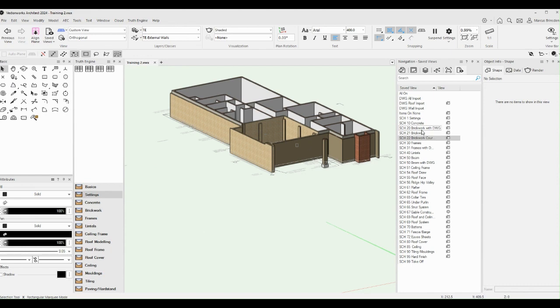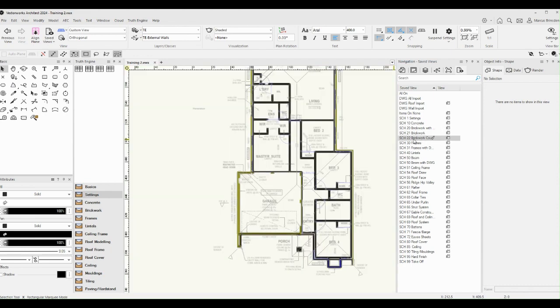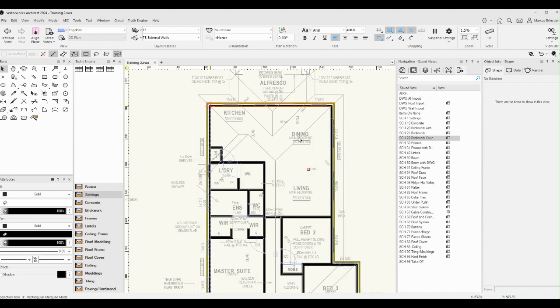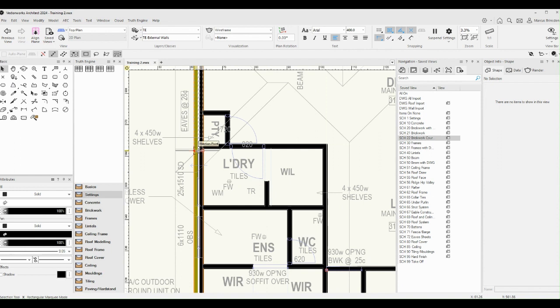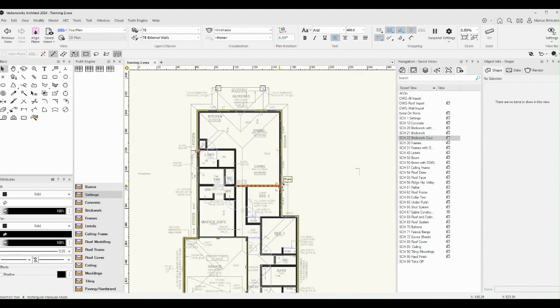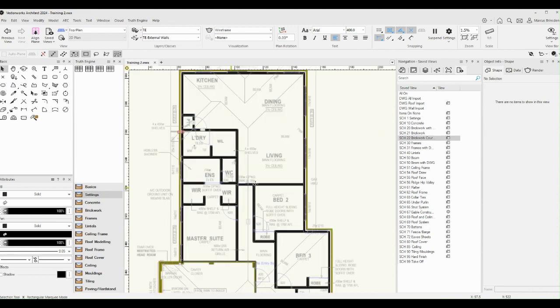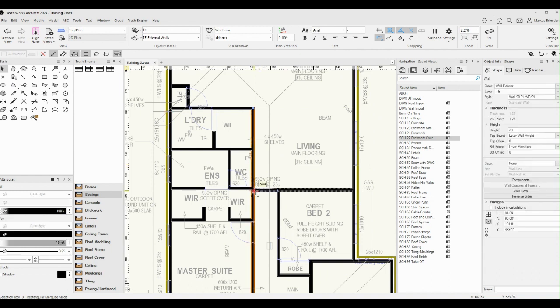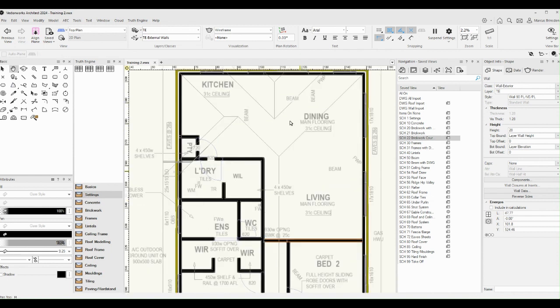Easy. Next, we have a 31 course high ceiling through this area here, as noted. So what I need to do is split this wall there, and I'm also going to split it here as well because it does change. Even though the eave height is the same, the ceiling height changes, so we'll split that as well. I'm also going to split this wall at that point as well. That wall's already split, so that wall, and that wall also need to be raised up to 31 courses.